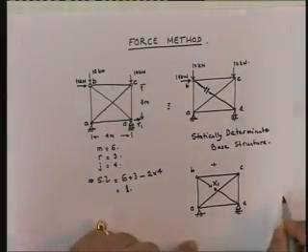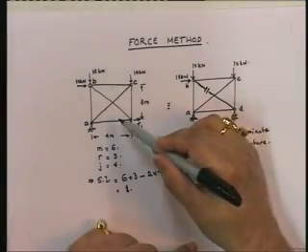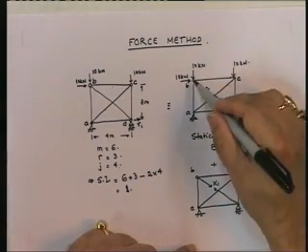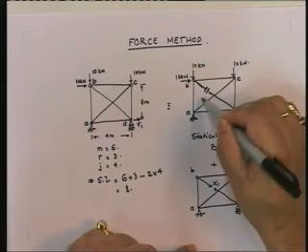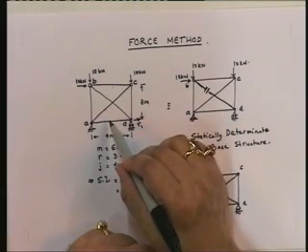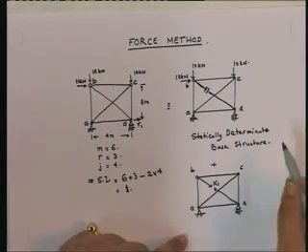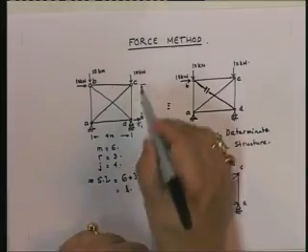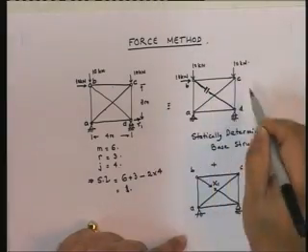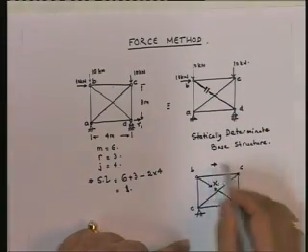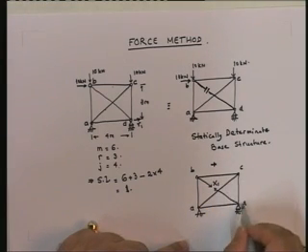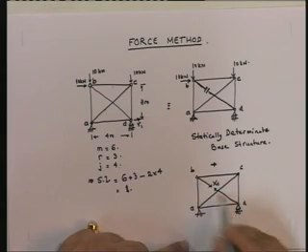So what we are saying is that from the original structure we get the statically determinate base structure, where the member BD has been cut so that there is no force in the member, and we say that, look, this original structure can actually be solved. You can find out the forces in these structures by finding out the force in the base structure plus the force in all the members and reactions due to the unknown force in member BD.